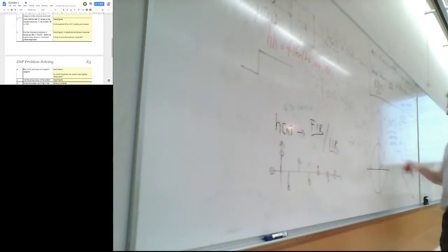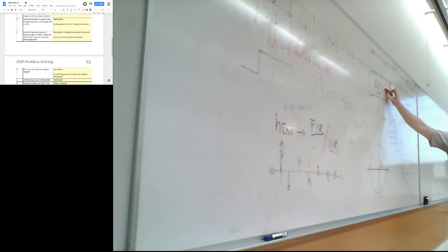Frequency response in MATLAB is freqz. I have no idea if I can actually use it today, but if not, I will just use Octave to show the general idea. Group delay, I think there is also a function for that, but that's actually also easy to measure.